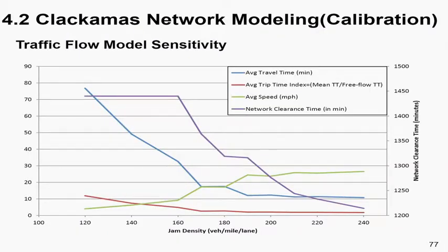But unfortunately, in the planning model, typically they code this as one lane, even if it's a two lane ramp. Even if you have a reasonable offload flow capacity, you have not considered this storage capacity well, and then we are creating these potential issues. That's why we need to be extremely careful when you try to convert from a planning package to a dynamic traffic assignment package.